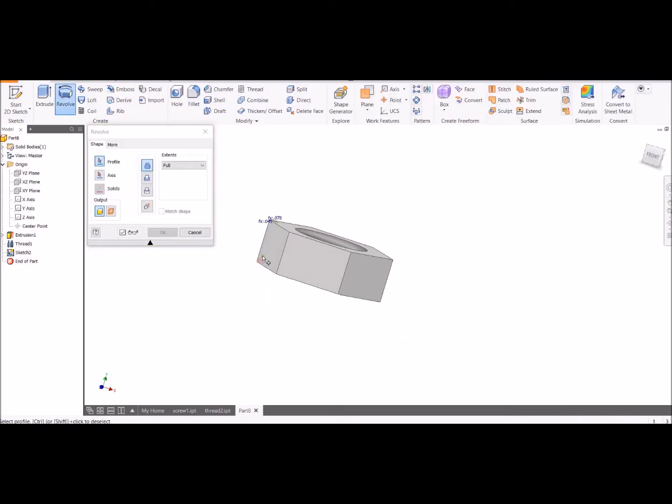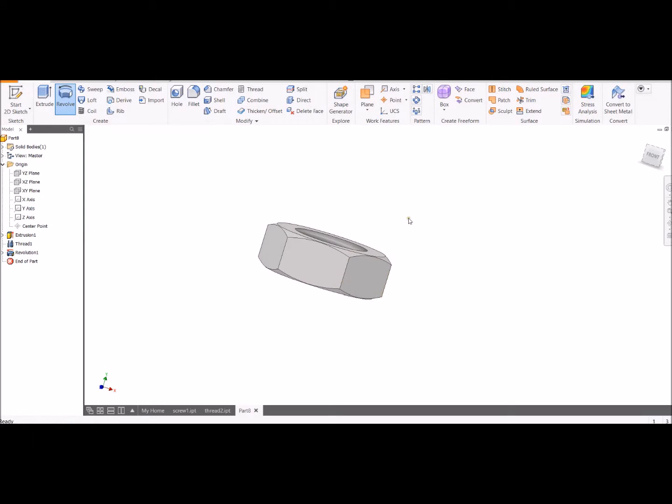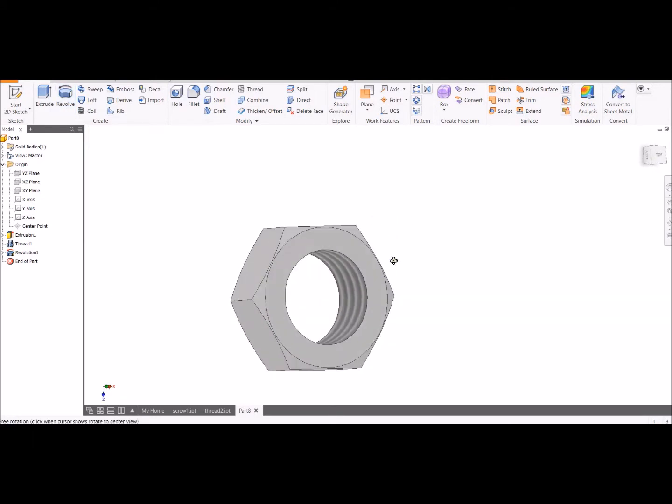and now I can go ahead and revolve both of those sides around. Let's see, I think I have an axis I can revolve that around. If I just use, is that the what? Yeah, there we go. Make sure it's a hole and not a solid. Okay, so there's a little bolt we can put on there.